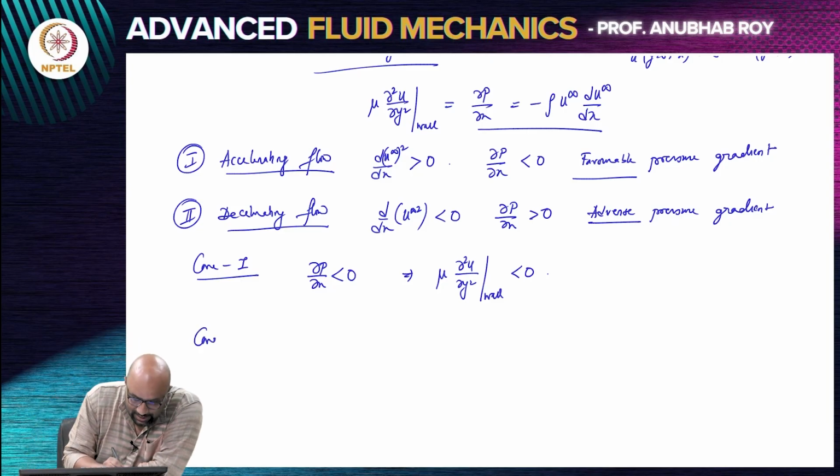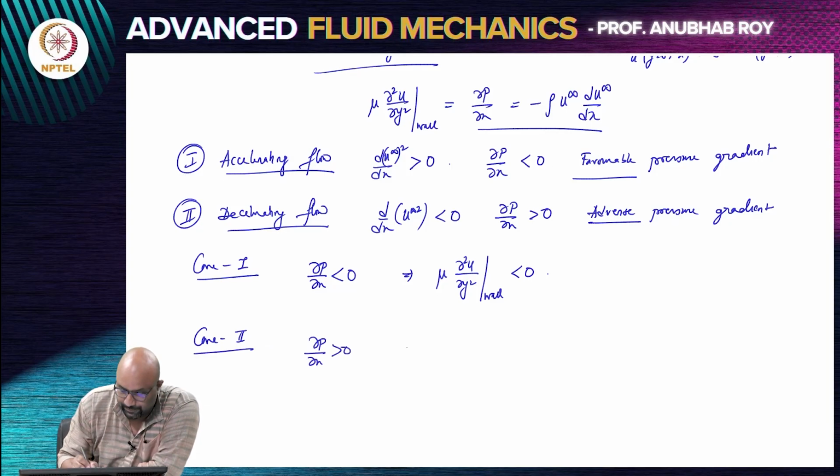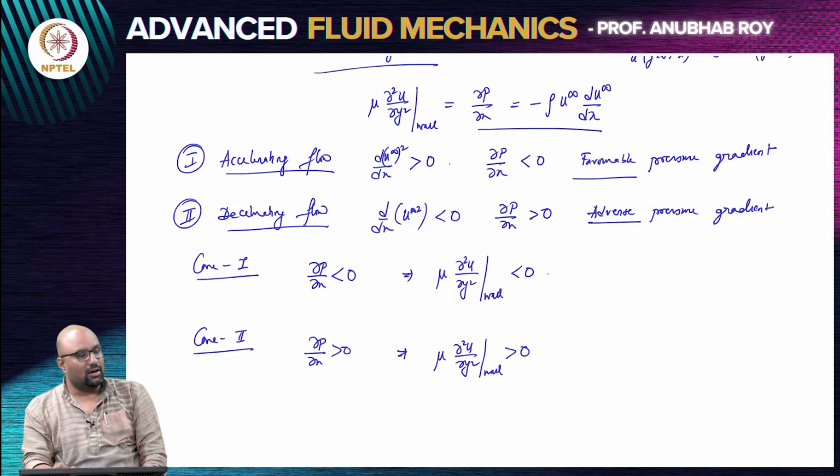If I have a decelerating flow where ∂p/∂x is positive, at the wall my curvature or gradient of shear stress is positive.